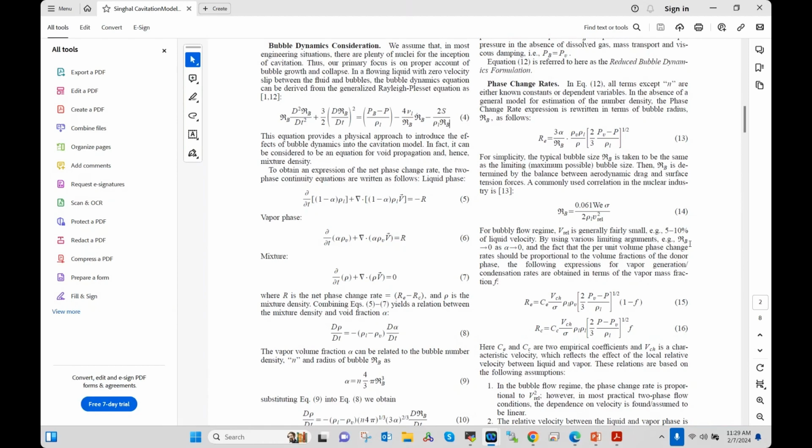Yeah, I think we have, I would say, 4 or 5 different variables that help us look at cavitation in more detail. So 0.5 is a number that we used, which means that it's very clear that there is cavitation happening. But if you use a lower number, that could mean that it's just the early phase, the early start of the cavitation. So I think this is something that we cannot say for certain. It's something based on looking at probably 2 or 3 different parameters together. We can make this judgment, basically, on which number is the best value to use.